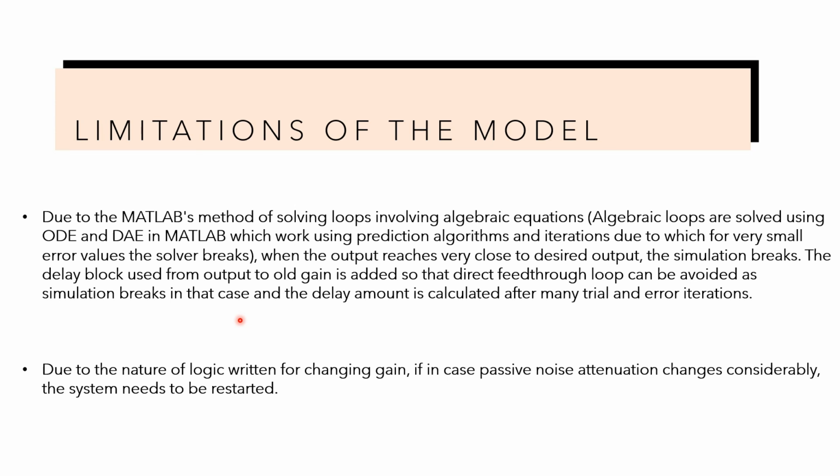What we saw was when we added the delay block, that is, we are not giving the direct feedthrough feedback, we are helping that algorithm to stabilize and detect proper values. Even then, the algorithm which Matlab uses fails when our error values are very small.